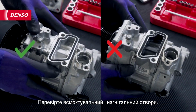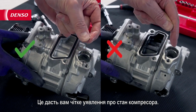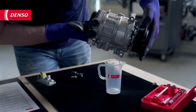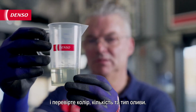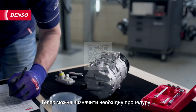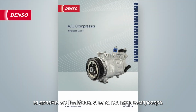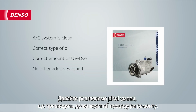Check the suction and discharge ports. These will give you a clear understanding of the condition of the compressor. Drain the oil and check the color, the amount, and the oil type, and write down your results. Once these steps are done, the visual inspection is finished, allowing you to determine the necessary procedure using the compressor installation guide. Now let's take a look at different conditions leading up to a specific repair procedure.